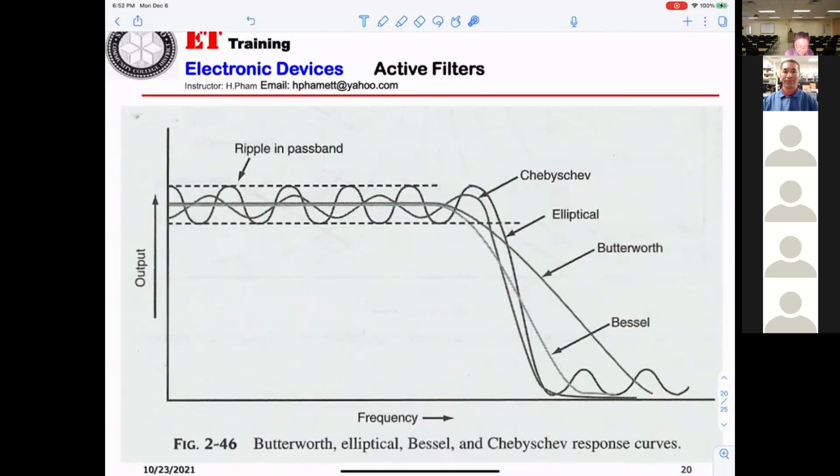So of all 4 of those filters, the Bessel is the one that's more correct how we want it. Right. Now you see the Chebyshev. They get a better cutoff than the Bessel. However, they get the ripple. You don't want the ripple. You don't want the noise. Okay? And also the elliptical. They get a better cutoff than the Bessel. However, they get a big noise.